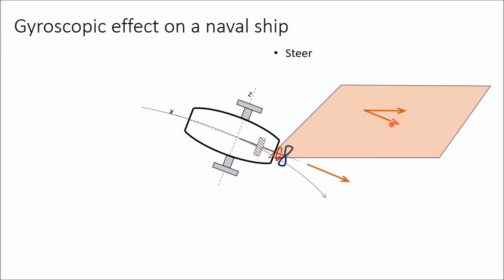Now the difference of these two vectors can be obtained by joining a line from the end point of the first vector to the end point of the second vector. So this is the difference, which is the direction of the active gyroscopic couple. The reactive gyroscopic couple will be just opposite to this. Now the reactive gyroscopic couple vector is acting on the horizontal plane. Therefore this reactive gyroscopic couple must be applied in a plane which is perpendicular to this, that is the vertical plane. So I have drawn this vertical plane, and this plane is perpendicular to the reactive gyroscopic couple vector.